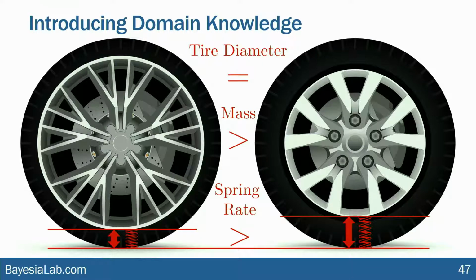The outer diameter is always fixed, but you have a choice of the size of the rim, which then affects the aspect ratio of the tire, basically the sidewall height. As you look at the left wheel tire assembly, there you have a very large rim. Perhaps that's a 20-inch rim. That leaves only a little bit of rubber at the bottom, so the sidewall is very short, as opposed to on the right-hand side, perhaps a 17-inch rim. There we have much more sidewall.